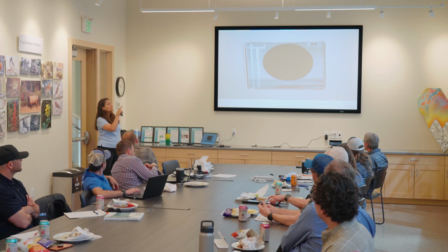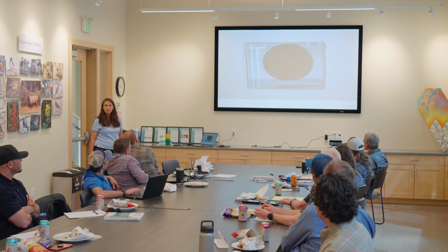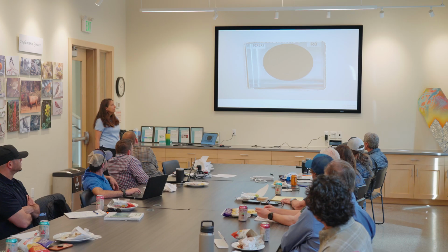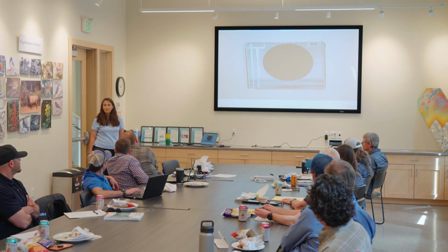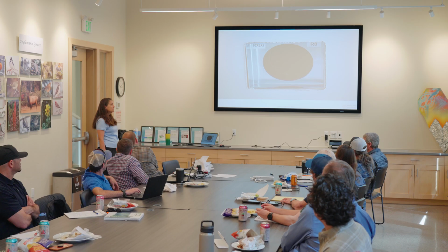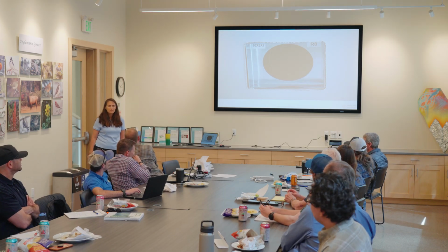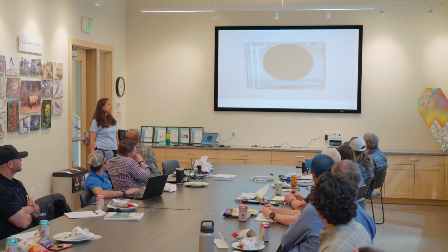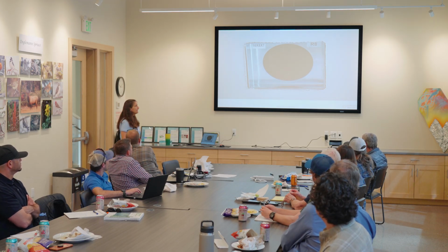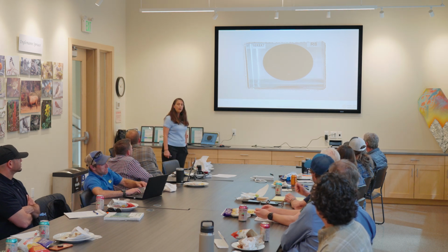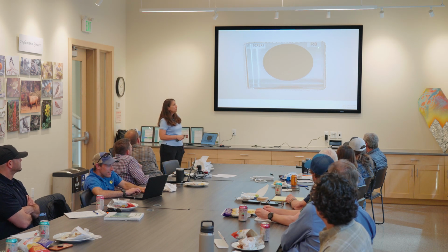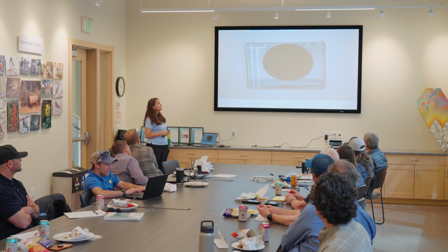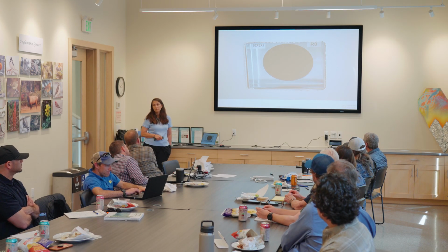Okay, if it was all sealed up, would we be okay with it? It doesn't have to be on there yet. If we're talking about insulation and we look at this, does it meet it? I don't see the insulation around the boom square. Okay, I'll give you that, but it is showing that it's an R8 right here. And we know that it has to be an R8 because look at the size that we have going on here. We know this is larger than 3 inches.